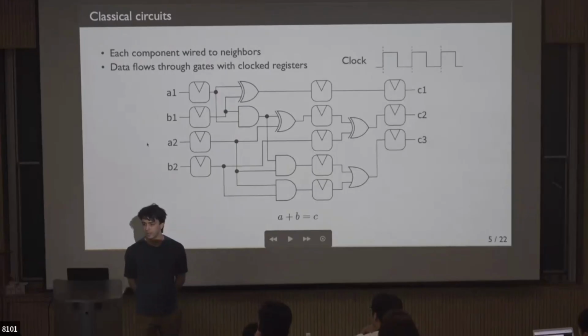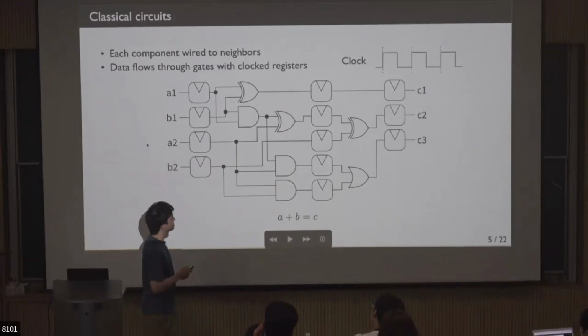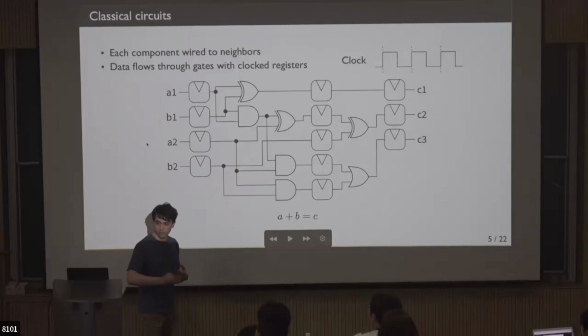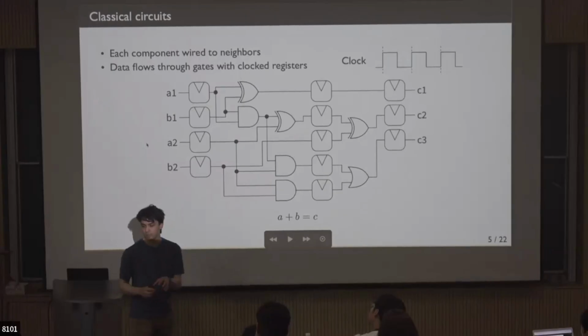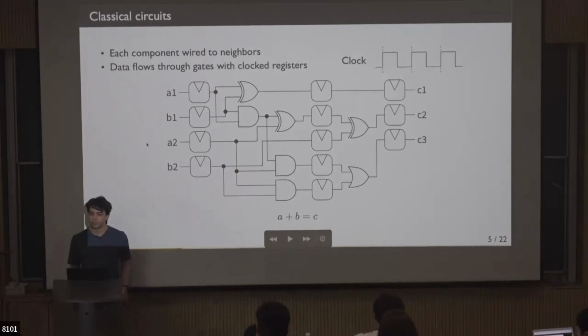For us, it'll be a little bit more fundamental, but the idea is that you have some delay to go from the input to the output, and you want to ensure that the data has settled in this period before the next rising edge of the clock. So it allows you to isolate chunks of the circuit and ensure that each one has the necessary delay. Yeah, so it's just engineering.